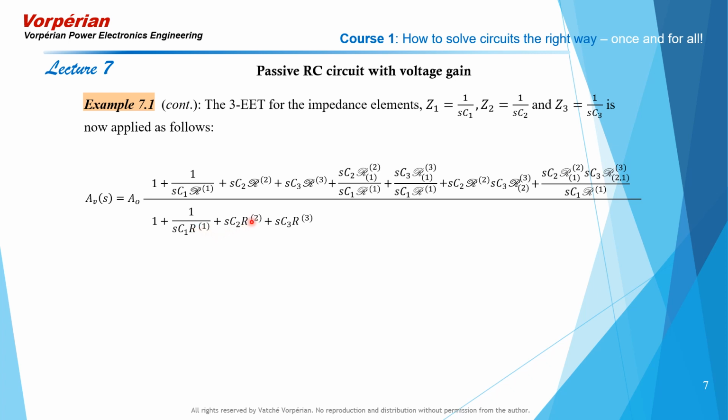These are ordinary driving point resistances. And then you pair them just like this, and then you take all 3 together at the same time. Now you can imagine the extension of the 3 extra element theorem to the 4 extra element theorem, for the 5, on and on. So next we're going to be computing all these port resistances.